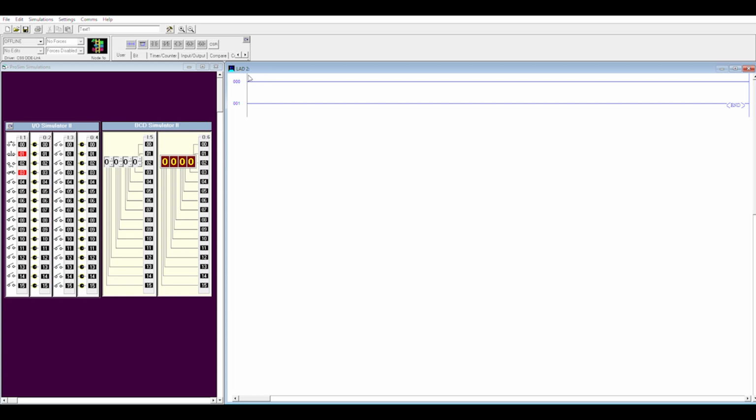So I've created a rung that I'm now going to edit. Remember from the previous little clip, we needed a branch in it. So I'm going to add a branch, and oops, unfortunately it added a whole rung. This is easy to solve. If I click on the previous rung that I really don't need anymore, if I right click on it, I can cut that rung, delete that rung, a little bit of a different terminology. Now I'm back to my rung, and it has a branch in it. I want to populate this branch. Remember, the first thing I wanted to do was have a pressure switch and examine if closed.